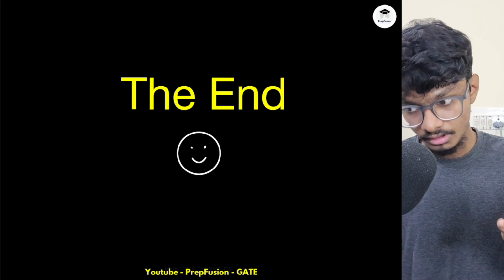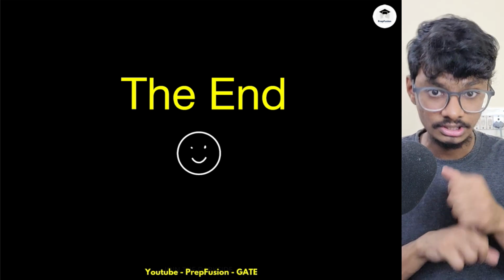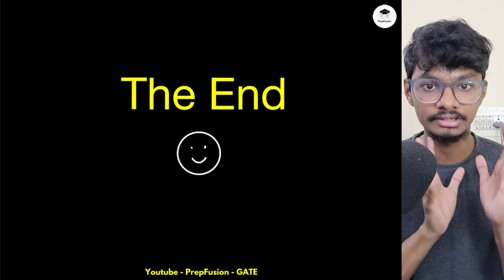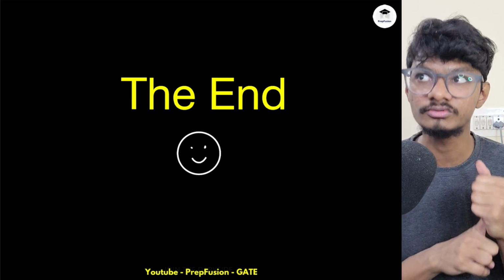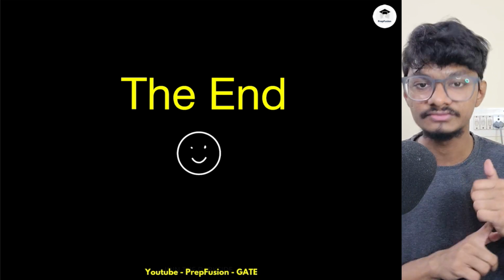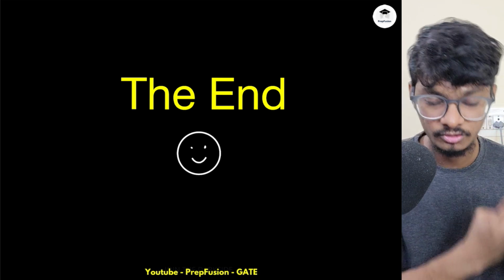So how do you write the short notes for this? Just write, like for ripple, right? You write VOAC by VODC. Then in your mind you think, okay, what was VOAC? VOAC was VORMS whole square minus VODC whole square. And you can find the ripple factor, you can find the ripples.